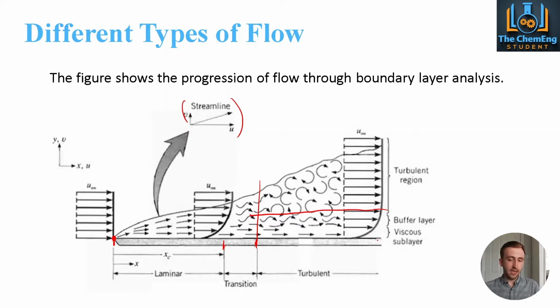So at the plate, we actually have a velocity profile of 0. So it remains pretty much laminar, even if we are in the fully turbulent region. It just, because the turbulence is so big in comparison to this small region, it is neglected. But you can clearly see that the arrows remain fairly laminar, but in comparison to these, they are heavily outweighed. So anything above the 3,500 threshold, we would have the fully turbulent region.